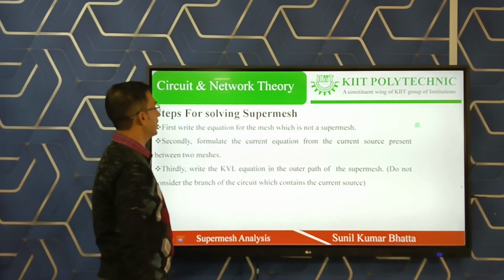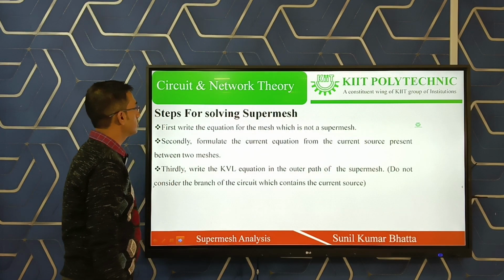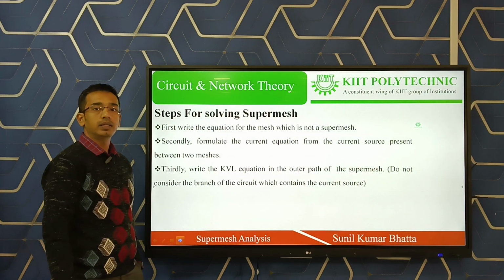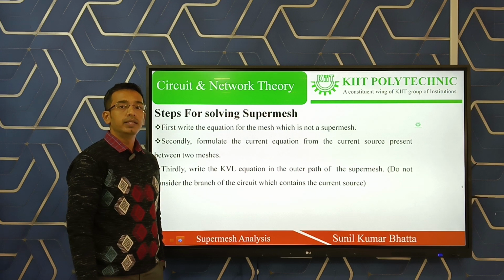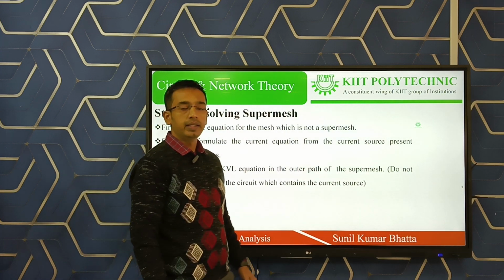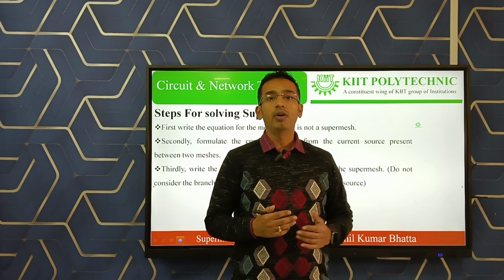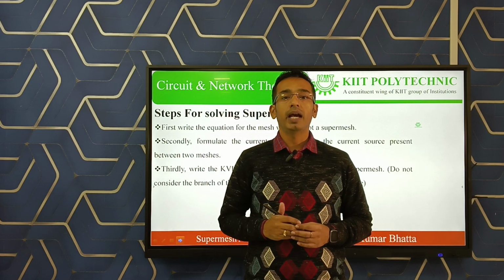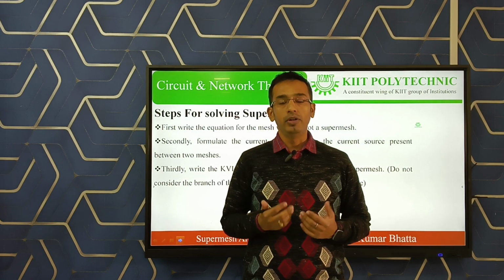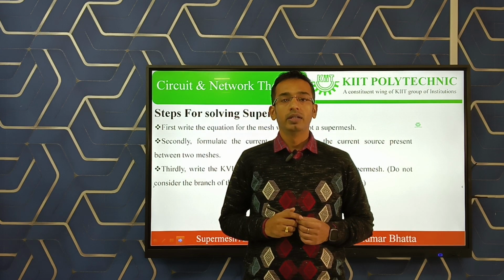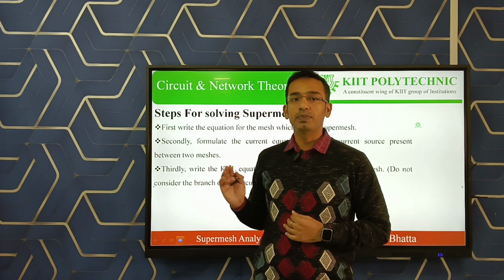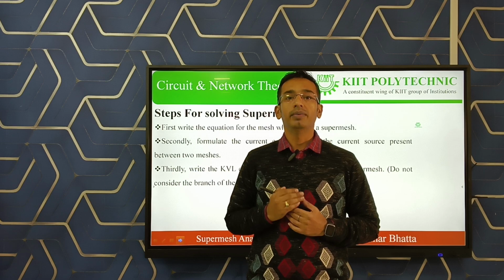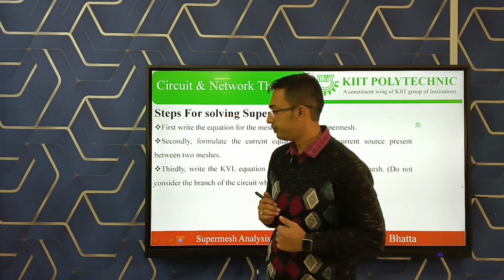Yes, coming to the next slide, that is the steps for solving super mesh. You can see here the 3 steps are written. These 3 steps will tell you how to write the equation for super mesh. Like in mesh analysis, by applying KVL we are able to write the equation. So by using these 3 steps we can write the equation.